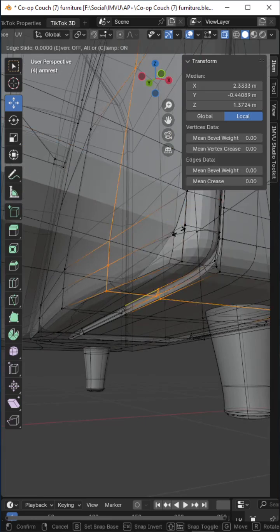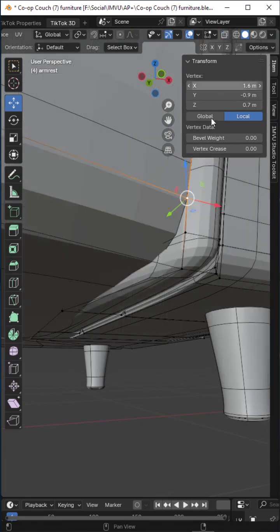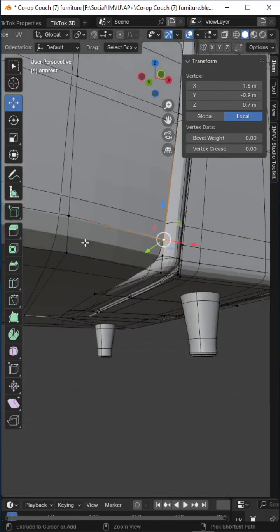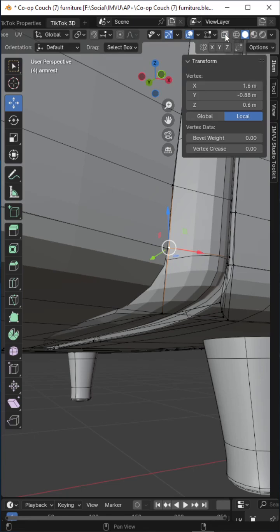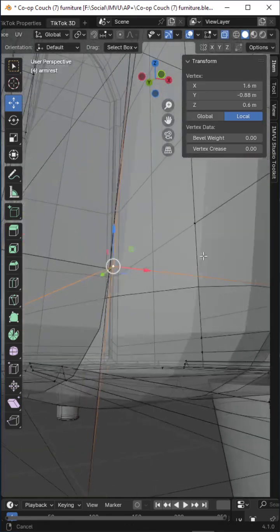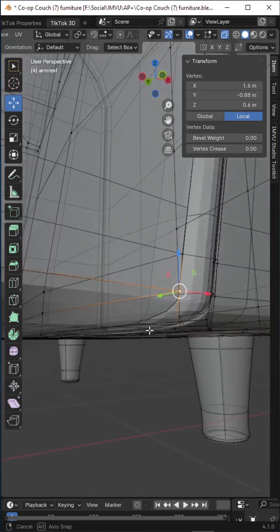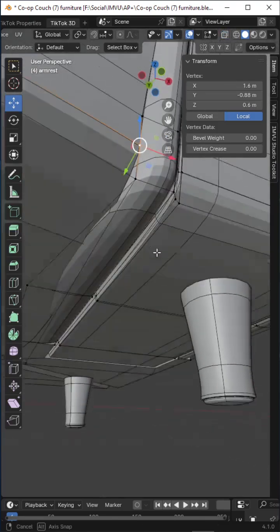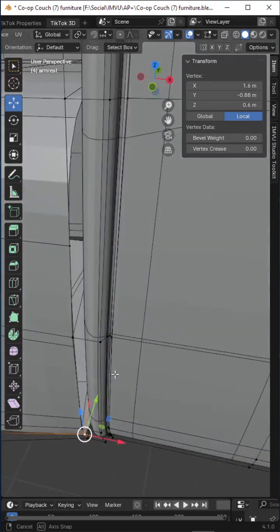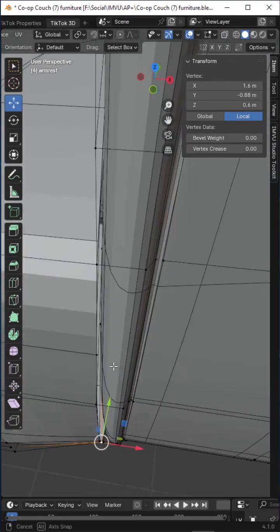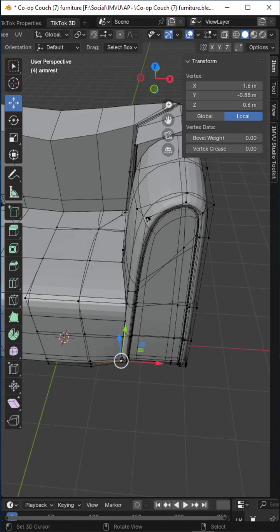Add another loop cut because whoops daisy. Undo because we want to replicate that curve around the bottom. Selection to active. So that'll give us a bit of a gap because of the way that the subdivision surface modifier is working.